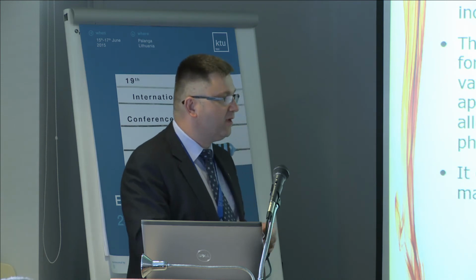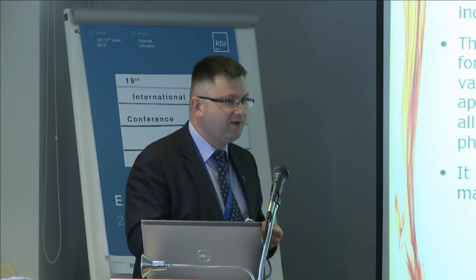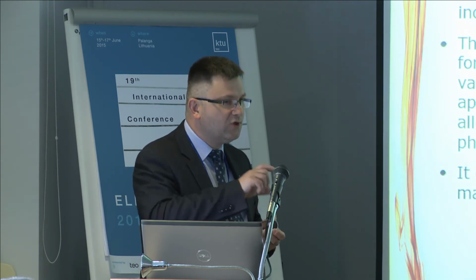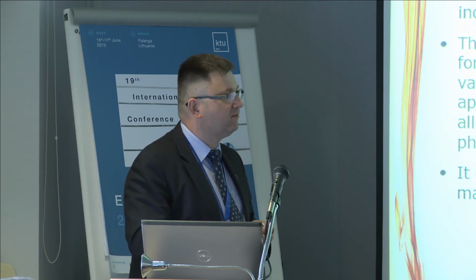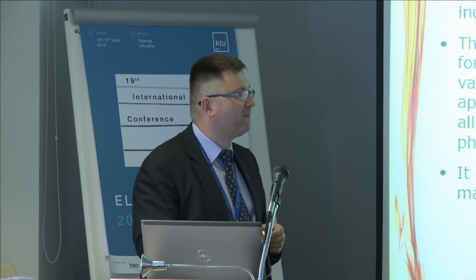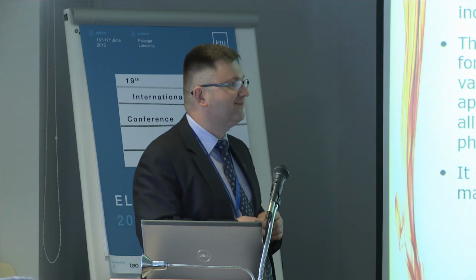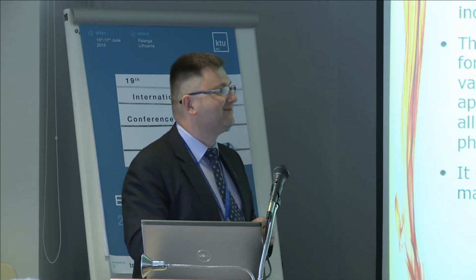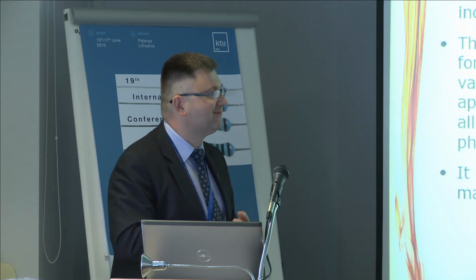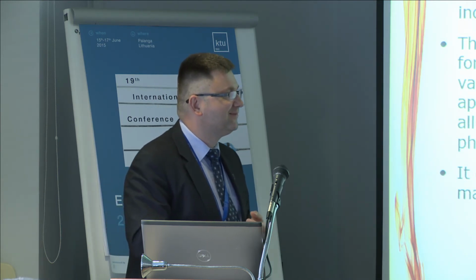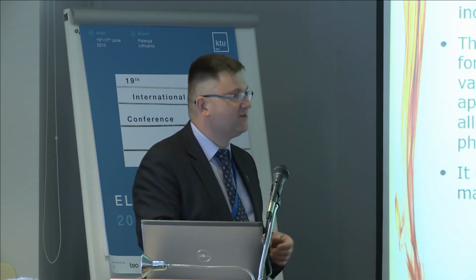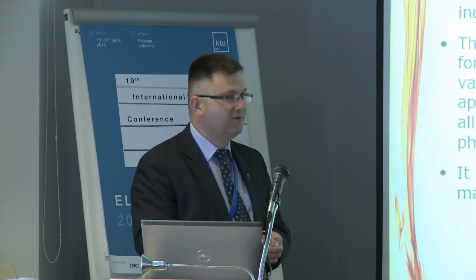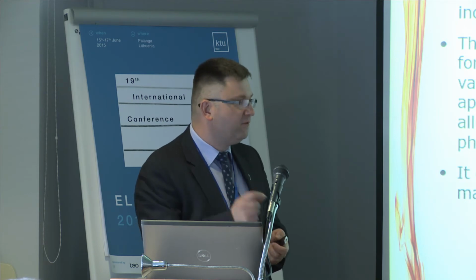You have to be aware of where to place your sensor, on which part of the machine, for example. And this is what you cannot always choose freely. Perhaps the construction of the machine leaves you a single opportunity to insert that sensor. But you can use another one, not this big, huge one. You can use a smaller one or a different kind.